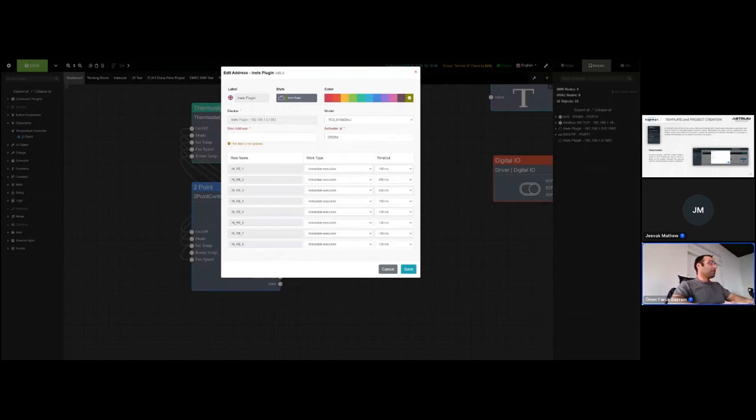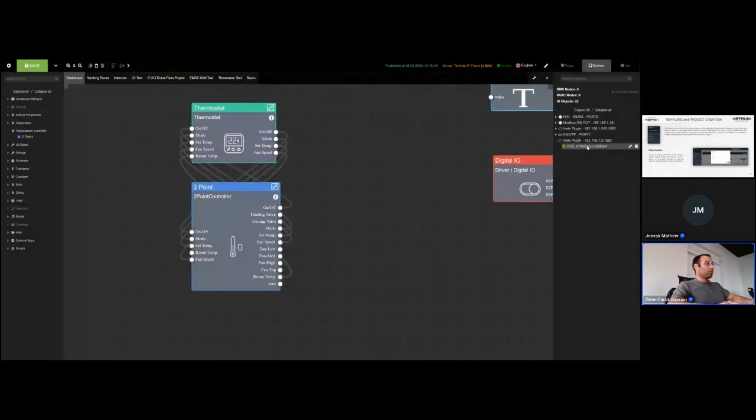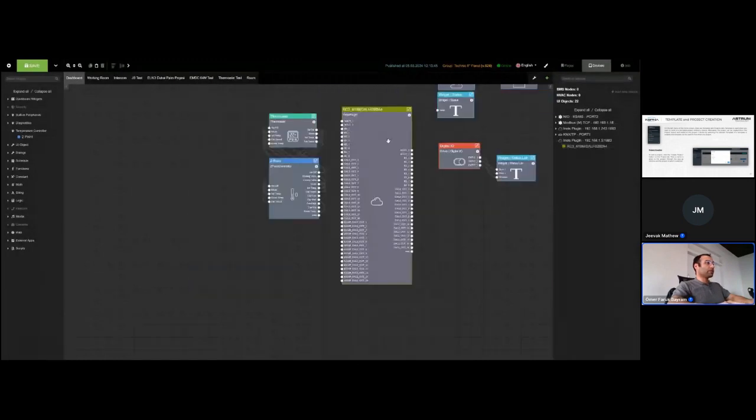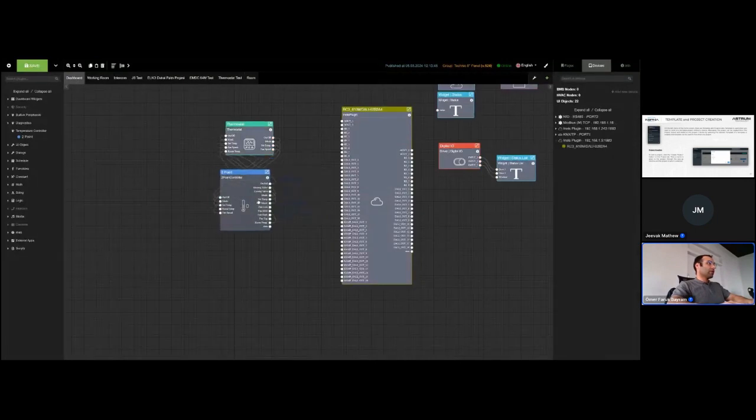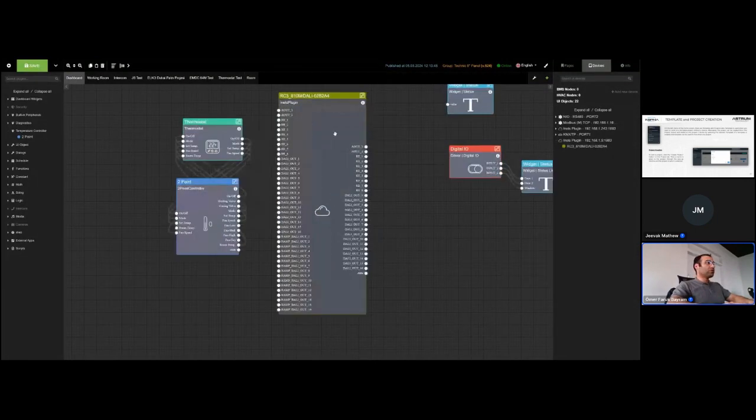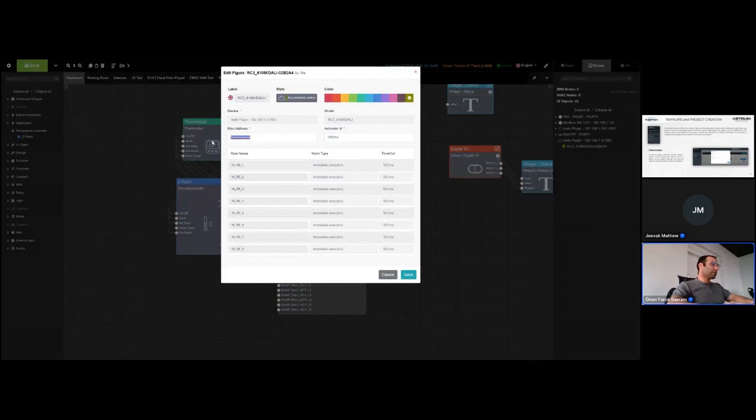We need to write here a MAC address. I'm going to write sample characters. After save, we will be able to see our object. It will come automatically. You need to write all information correctly, and you need to cable all Ethernet and bus correctly. If you did something wrong, you cannot connect the device. So these are critical information.